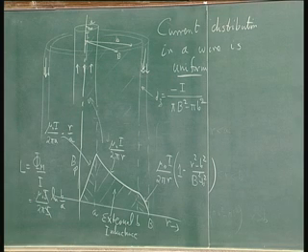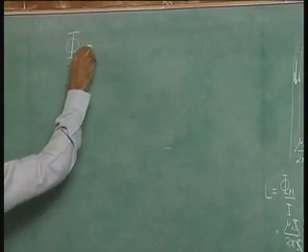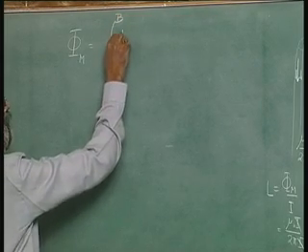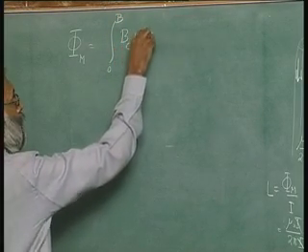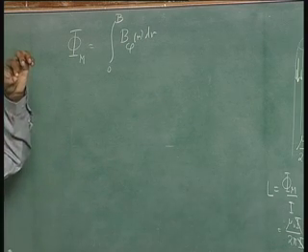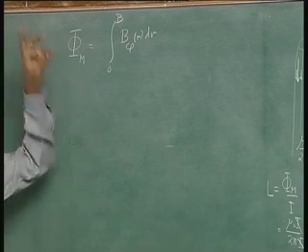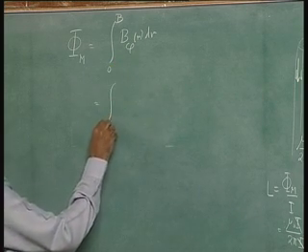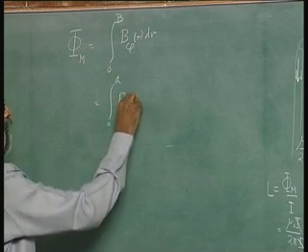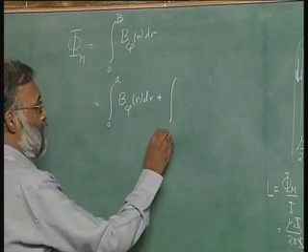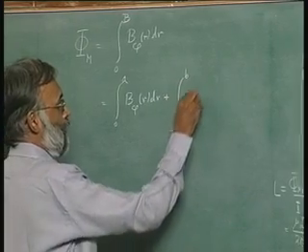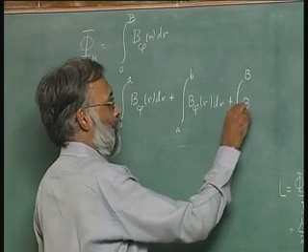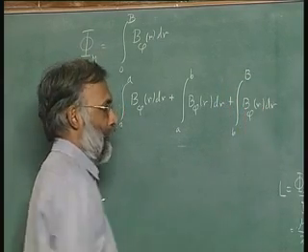So, I will say that the flux phi m is equal to the integral 0 to capital B of B phi of r dr. I am taking per unit length of L in the z direction. So, it breaks into 3 parts. There is a part going from 0 to a, B phi of r dr, plus a part which goes a to b, B phi of r dr, plus a part going from b to capital B, B phi of r dr.